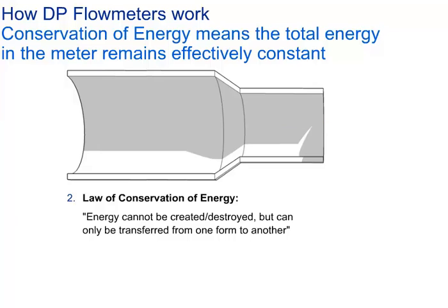We've already shown that as a fluid passes through a restriction, it must accelerate. An increased fluid velocity means that its kinetic energy has increased, because the kinetic energy is proportional to the square of the velocity, i.e. half times m times v squared. This increased energy must come from some other form of energy present in the system. It actually comes from the pressure, which is therefore reduced in and around the restriction. So a local increase in velocity will produce a reduction in the local pressure.